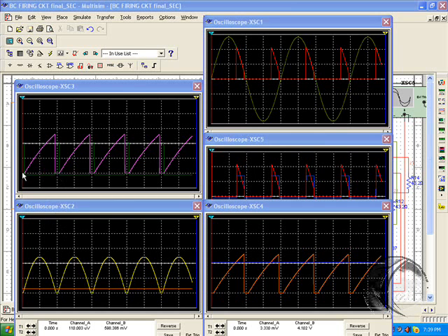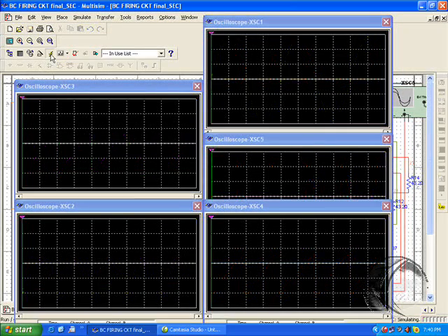And we know we get sawtooth voltage when we pass it through a transistor switching, and that sawtooth voltage is again compared against certain fixed voltage which generates this kind of output pulses, and ultimately if it is a DC, that means two diodes and two SCRs, then we get from the AC this kind of DC. We will see now while we simulate, the idea will be clear.